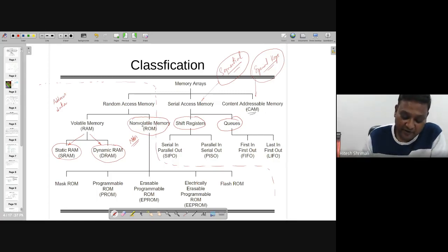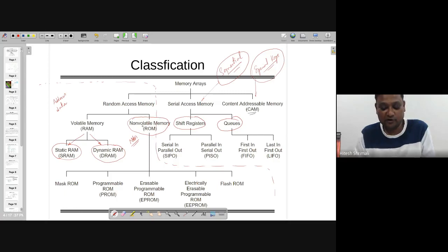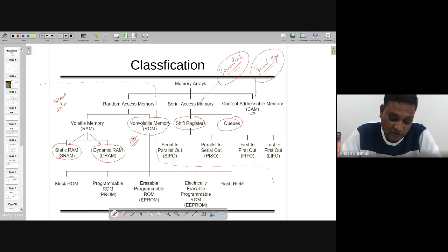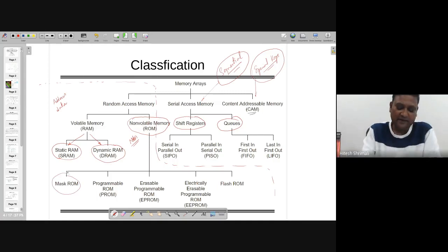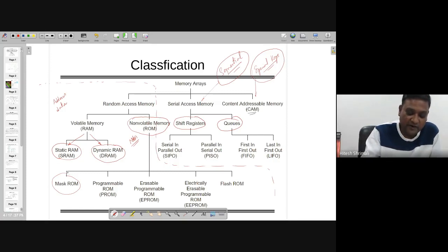And in the case of non-volatile memories, notably, this is also given in the book, and that's the next slide I copied also. Non-volatile memories are not completely non-volatile. They can also be programmed, and you can read and write also. So it's not completely non-volatile, and it depends on different conditions. The first class is the mask ROM, which has been fabricated with hard wires, and afterwards you cannot change it. However, the programmable ROM, you can program with some kind of fuses inside the memory.